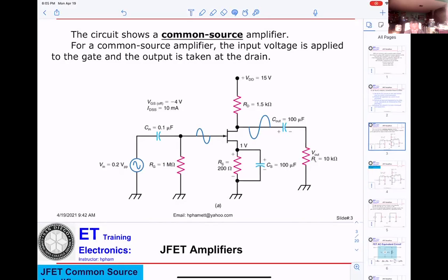You're talking about the cutoff frequency? Right, the assumption here is that the frequency of the source is so far above the cutoff frequency that the capacitor is a short circuit. It's not filtering. Is that correct?